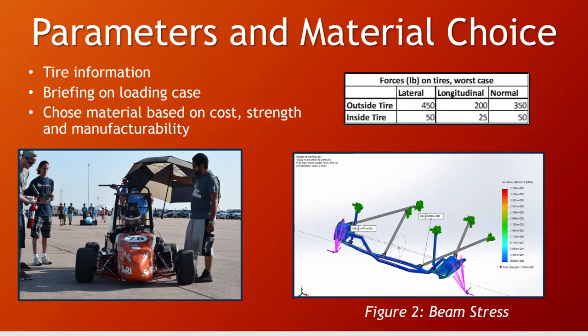For example, if going around a corner, this friction capability will be split between lateral and longitudinal tractive forces developed by the tire. Using the peak coefficient of friction, a known weight distribution front to rear, and the vehicle weight, it is possible to find values for the tractive forces at the tire contact patch. The lateral, longitudinal, and normal forces will all contribute to the behavior of the car. The normal force on a tire will dictate the maximum tractive force that can be developed laterally and longitudinally.